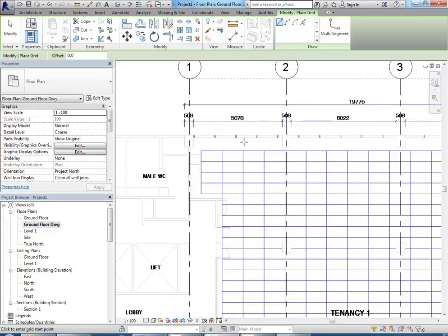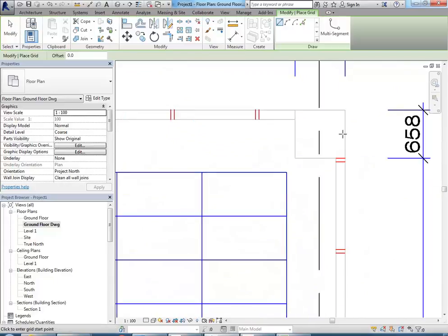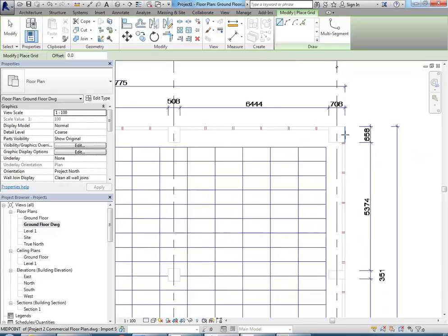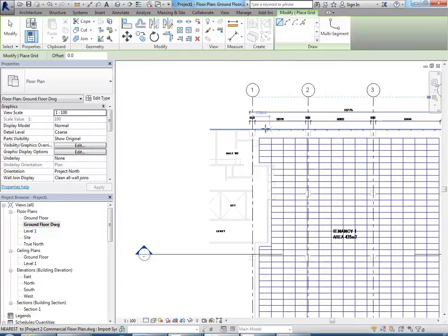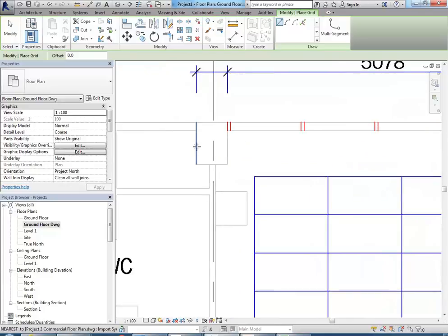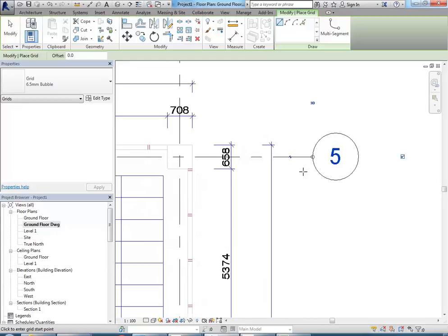And so then I've got the grids going the other way, so I'm going to go into one of those columns there, and again just from the midpoint, deciding which way to go. I think we'll go to the right. So I want my grid bubbles to go outside over on the right over here. So I'm going to start on the left, find the midpoint of that column, and then go over to the right, and then just place the bubble out there. So notice the bubble always goes onto the second point that you choose. That's why I'm just making a decision about which way to draw.